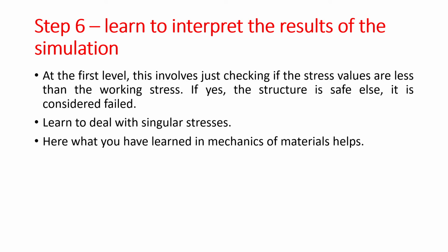Next stage, step six, you learn to interpret the results of the simulation. At this stage, whatever material failures you had learned in mechanics of materials, whatever structural failures you had learned in the design of machine elements, all those things you apply here, and you predict if the structure is safe or not.